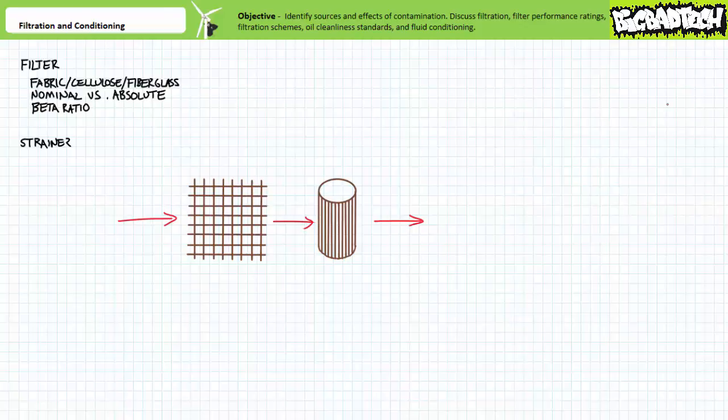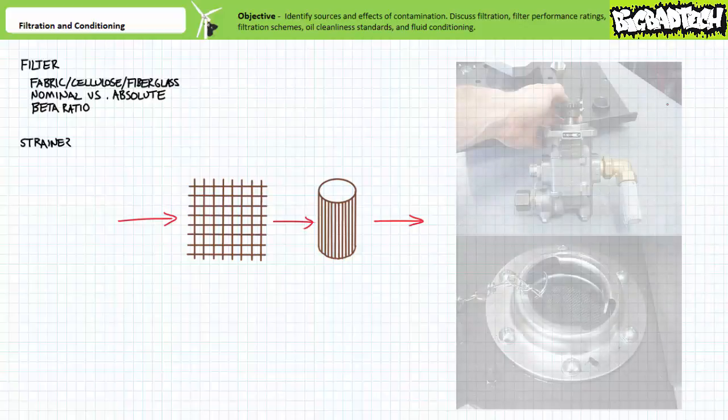Strainers are elements very similar to filters, however, are ordinarily designed to exclude only large particles, generally 50 microns and above. Strainers are basically wire mesh fittings which offer less resistance to flow than a regular filter. Strainers and filters work in combination by allowing the strainer to remove any large contaminants that may easily clog the filter and letting the filter handle all those smaller particles the strainer fails to catch.